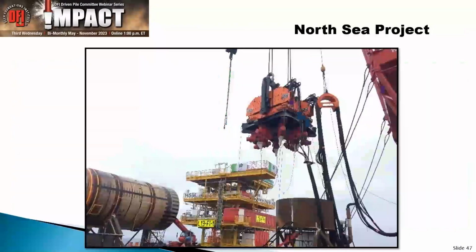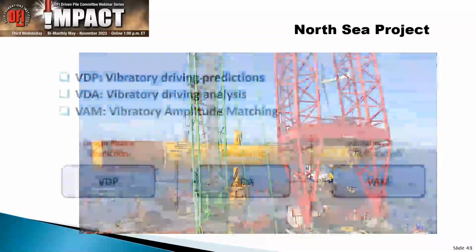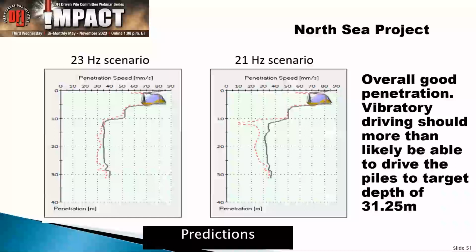So as I've modeled these land-based vibratory conditions, I see that they're very sensitive to the clamp weights. Is that because of the weight of the clamps relative to the weight of the hammer, or is it something more complicated than that? I mean, does sizing a clamp on an offshore hammer by 15% in weight greatly affect it like it does on land? No, on land or offshore, you have different sizes.